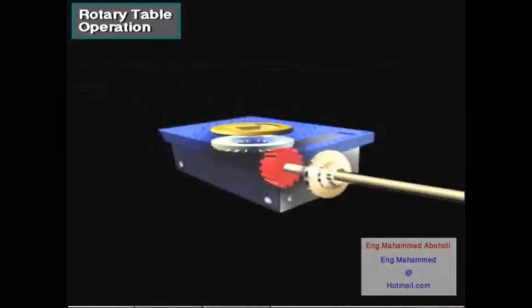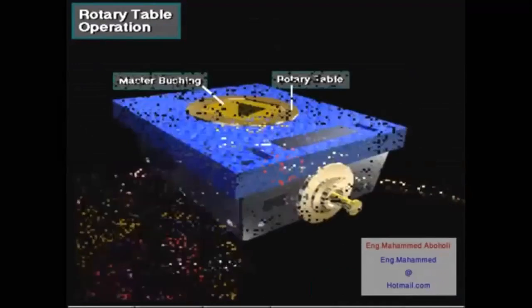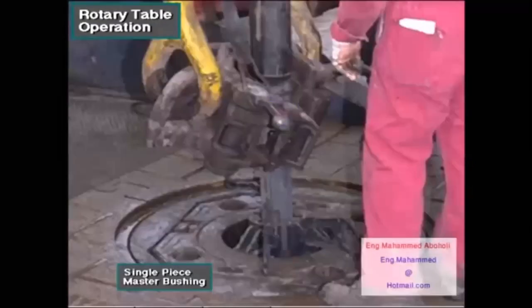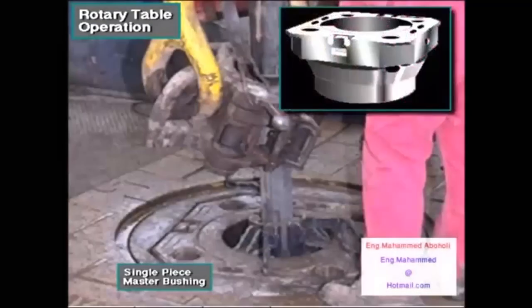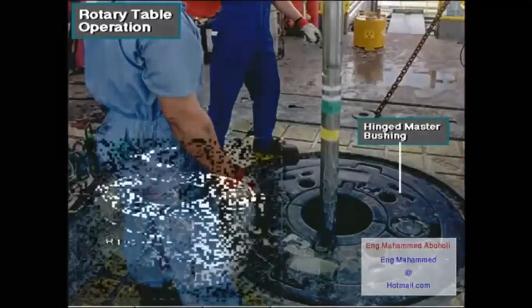The rotary table performs 2 functions. First, it transmits rotary motion to the master bushing, which drives the Kelly and drill string, and, with assistance from slips, hangs the drill string. The master bushing goes inside an opening in the rotary table. Small master bushings are usually a solid single piece, as shown here. Large master bushings are either split or hinged.